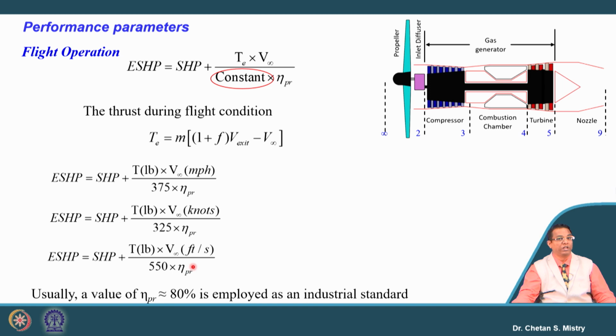Now usually this propeller efficiency we assume to be 80%. That's a common practice. If you are able to have your propeller efficiency calculated by testing or by design, you can select that number here.